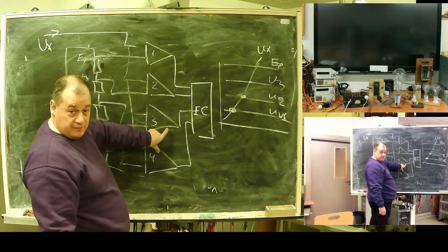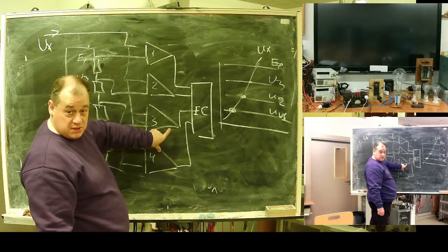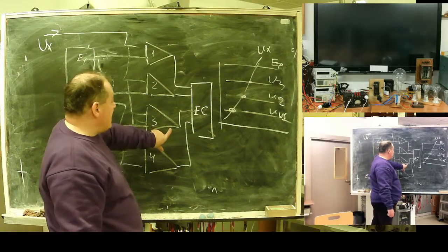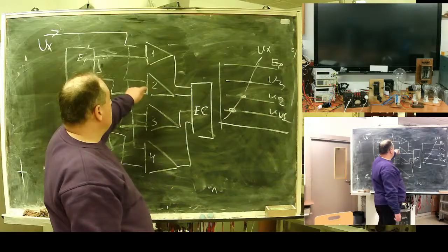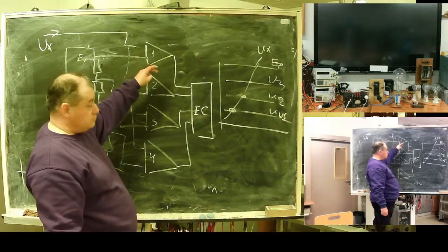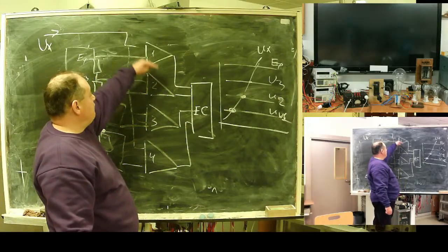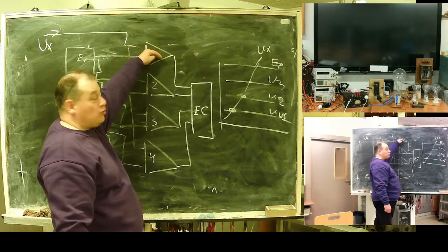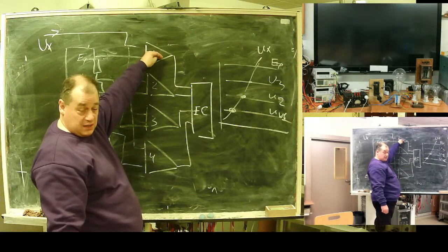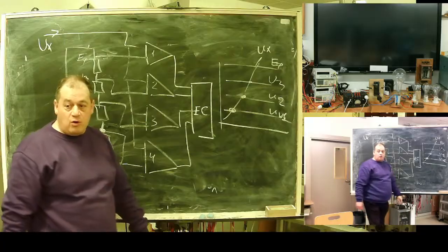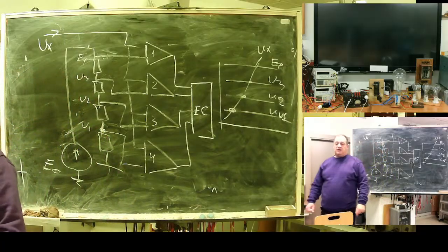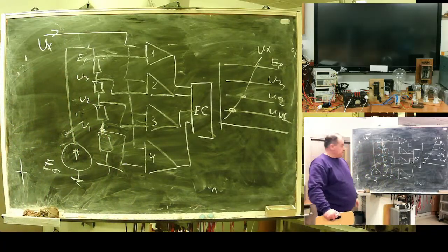What does it mean? It's impossible. This means error. So error check checks what? What if we have trigger on high level comparator? All low level comparators are also triggered. If not, it's a fault.